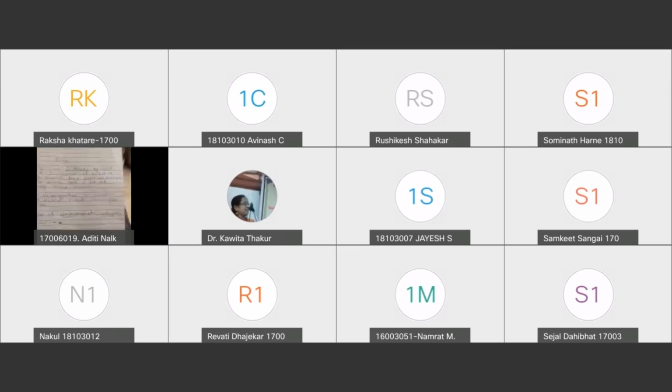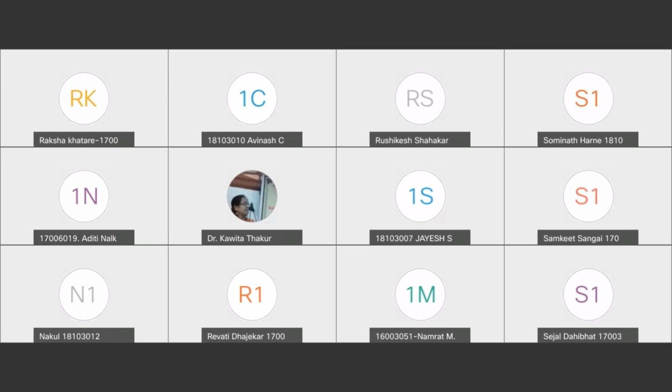A relay is an electrically operated switch. It consists of a set of input terminals for a single or multiple control signals and a set of operating contact terminals. Relays use electromagnetism to convert a small electrical stimulus into a larger current. Then we see the principle of electromagnetic induction.